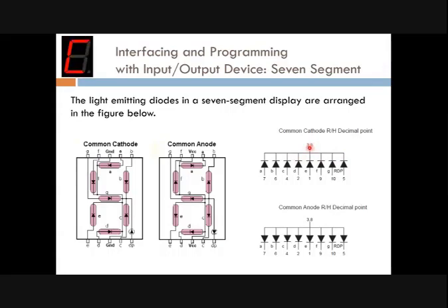Okay, so for 0 or logic low, you can connect directly to the microcontroller, and if you want to avoid connecting to the microcontroller, you can use just a typical ground. And then for common anode, you can see the anode part connected together, and this one can be connected to a logic high 1 or source. And then in order to activate, you need to give logic 0 in order to light up.